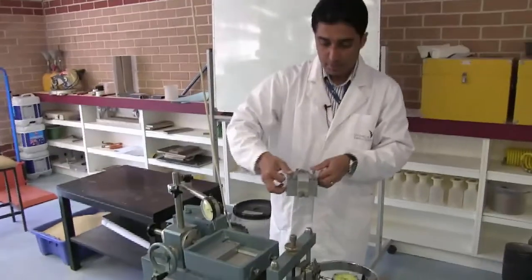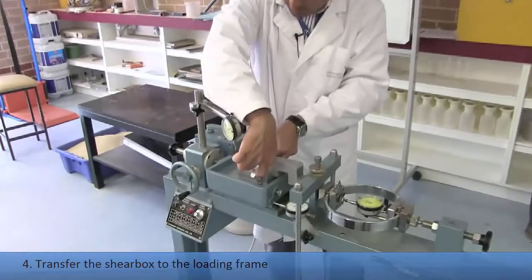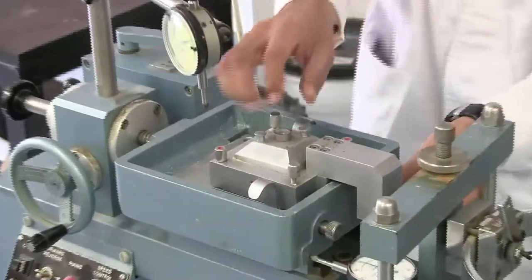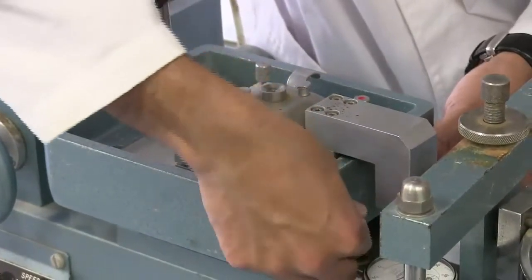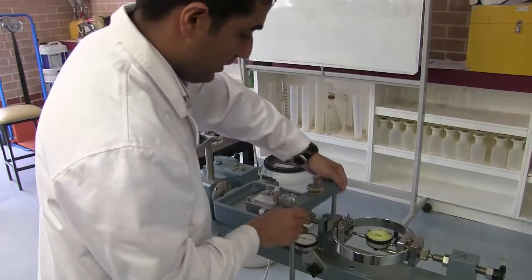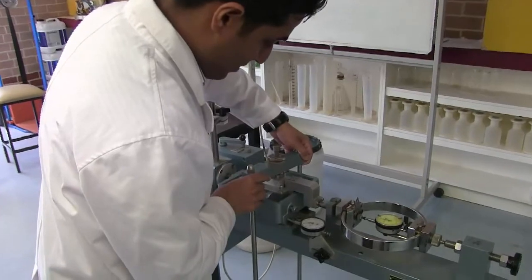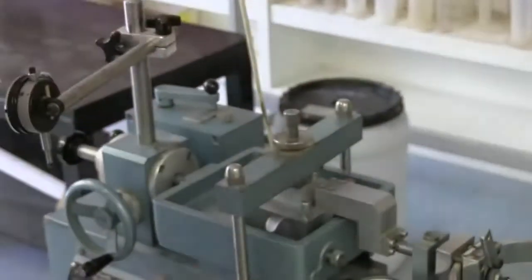So now gently place the shear box in the testing apparatus and make sure it places correctly in the tray, and then tighten these screws. Once you did that, place the loading tray on the soil sample, gently like that.